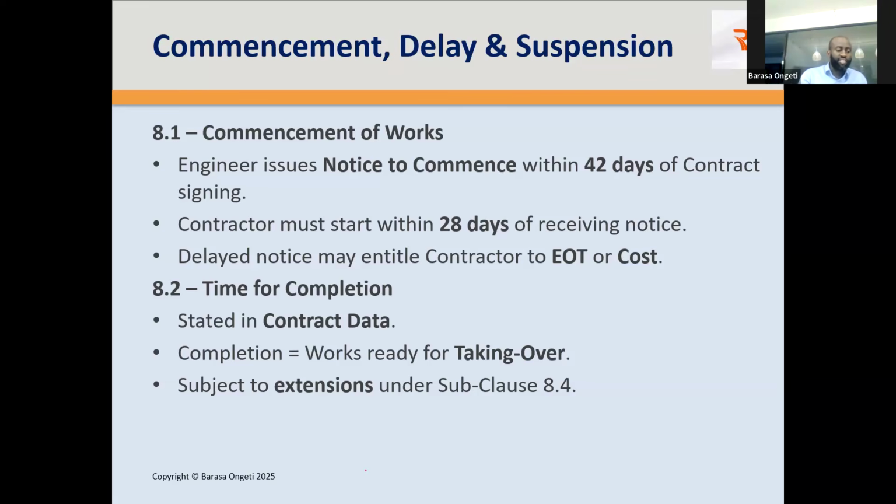It's provided the contractor has given the performance security within 42 days. And once the contractor has received the notice to commence, they have, I believe it's 28 days, yes, they have 28 days to start the works and proceed with due